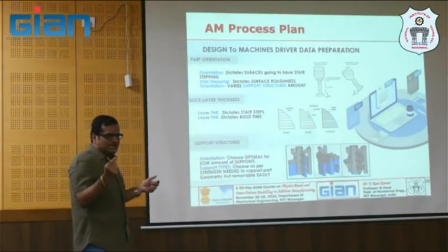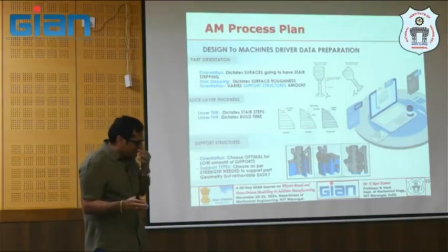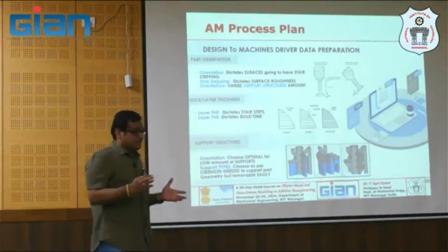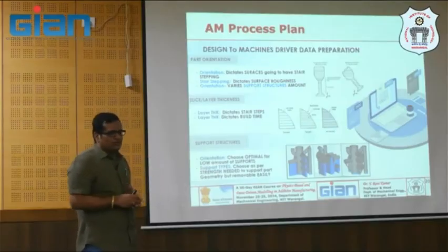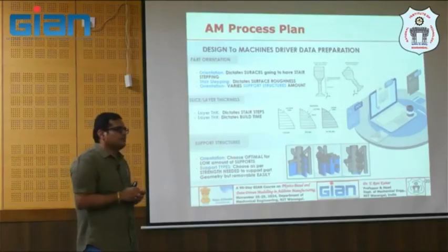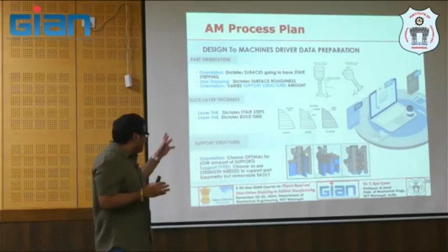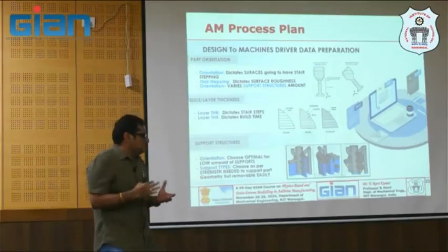And slice thickness, of course, more or less it is uniform slicing. All proprietary machines will support only the uniform slicing method, but it could be a kind of adaptive slicing, or a region-wise adaptive slicing kind of algorithm. But I am not sure whether proprietary machines will support such varying layer thickness between the layers.